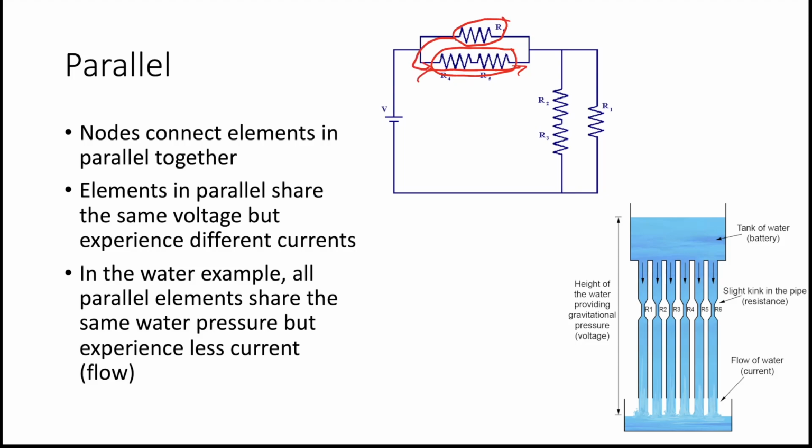The same thing is true for the one on the right. Resistors 2 and 3 are in series because the same current flows through both of them, but resistor 2 and 3 are in parallel with resistor 1 because when you get to this top point, current can split as necessary, and it will recombine down here, and the current will flow back to the source.